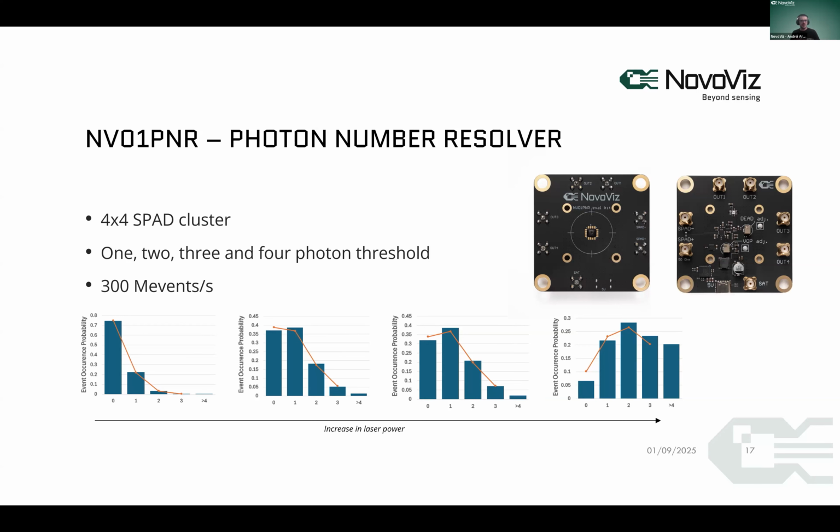And on the bottom, you see an example where we've directly coupled this detector with a photon counter, like a time tagger, so 4 channels simultaneously. By counting these pulses, we can essentially see a histogram. We can see the Poissonian distribution of the photons as they land on the detector while we adjust the laser intensity. And the curve that you see there is not fitted. It's actually just a direct plot of a Poissonian distribution that has the same average photon count as we measured, and it fits very well at the low light level.